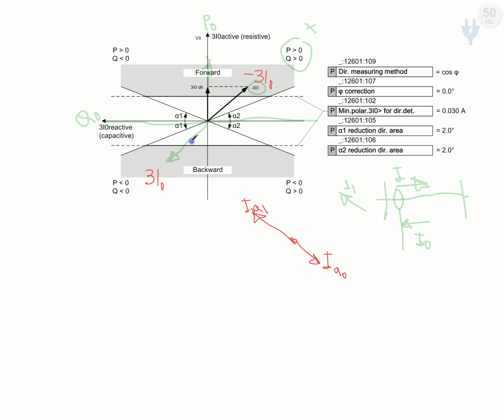So actually here it is in the opposite direction during the fault, but the relay should take it as a lagging value by V0, that is, we give a negative to the value of 3I0, and this is the angle phi. We know that this phi is minus, and we know that our symmetrical axis is this axis.